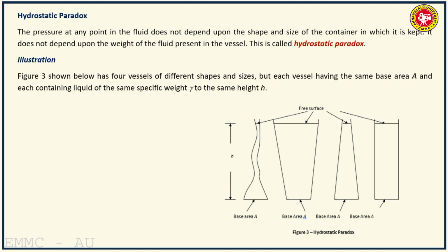What is hydrostatic paradox? The pressure at any point in the fluid does not depend upon the shape and size of the container. They do not influence the pressure. It does not depend upon the weight of the fluid present. Pressure depends upon the specific weight of the fluid, not on the weight of the fluid. So let us illustrate this hydrostatic paradox and understand what it is by this figure.